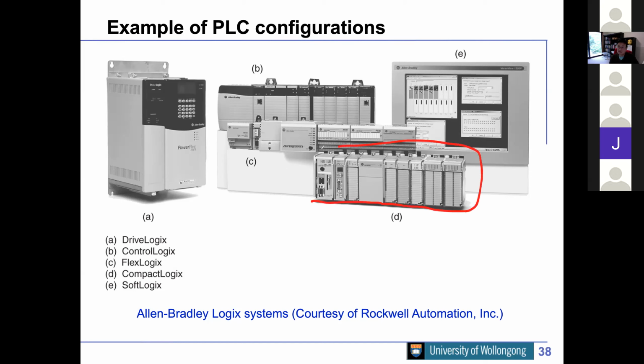It's an expandable module. You have your main computer, you have your communication card, and all these input-output terminals. You can connect to many different inputs and outputs, and it's expandable. You can have more modules next to it if you need to expand. So it's like a computer, but its strength is only input and output control. This figure gives you a few examples of Allen Bradley PLC.